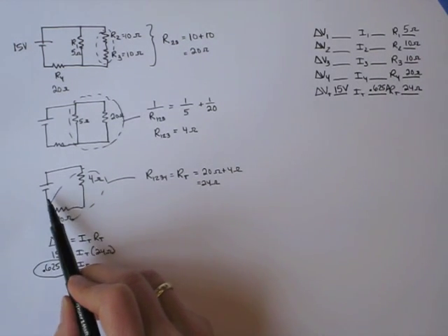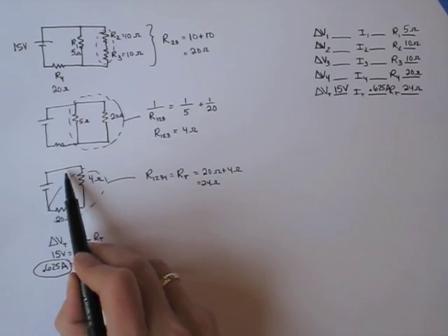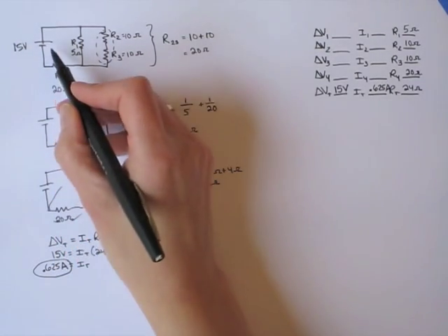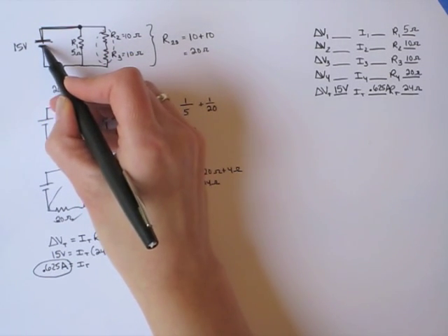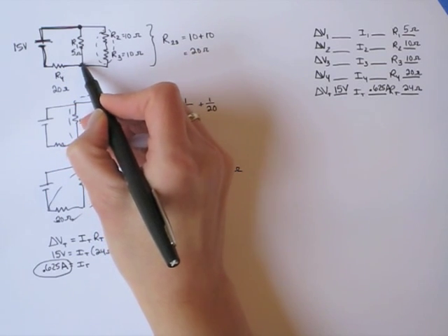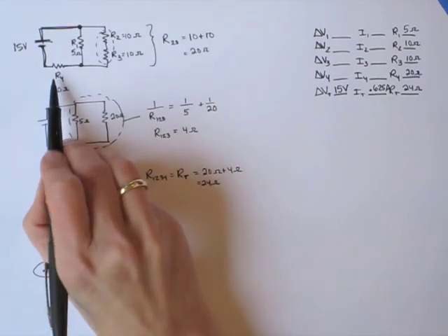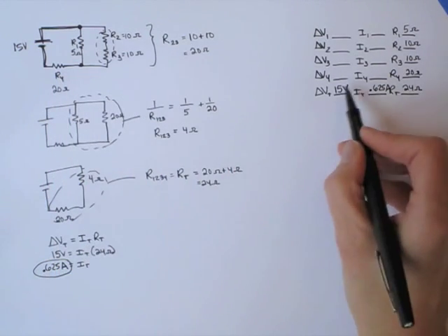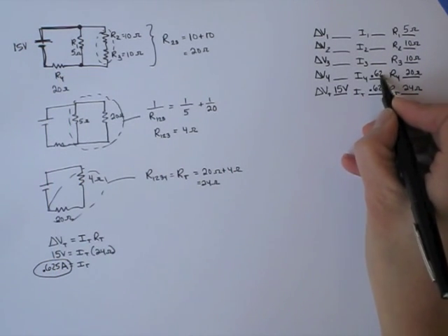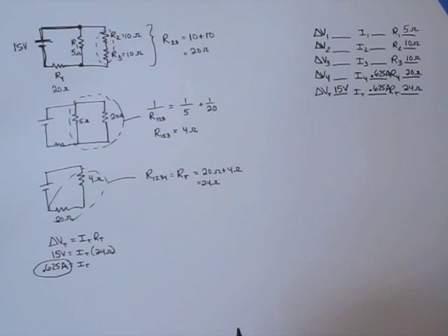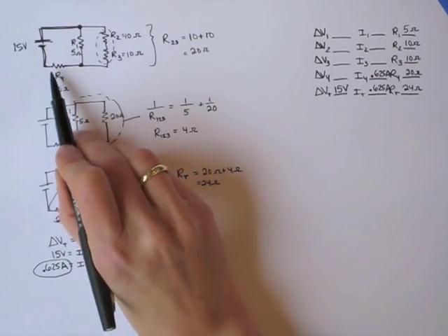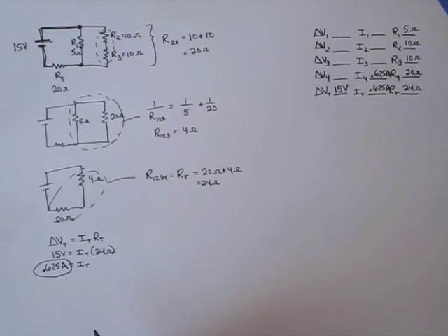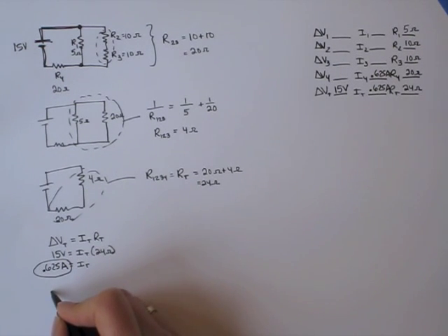And now we need to look at our circuit diagram, and we can see that the parts of the circuit that have this total flow are up here before that branch and down here until this branch. So the total flow goes through R4. So that means we know the flow through R4 is 0.625 amps. Well, if we know the flow through there and we know the resistance, we could find the pressure difference across that resistor, or the potential difference. So let's go ahead and do that.